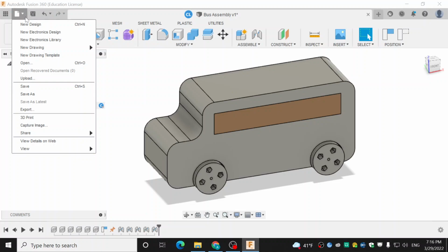And it takes a little bit longer because this part is relative to another part, and you have to have the meshes of both those things, and it just takes longer and longer the more you add. Interesting. So that's why I usually say it's better to just export the parts individually. But you can do it if you just do file export for the whole assembly.